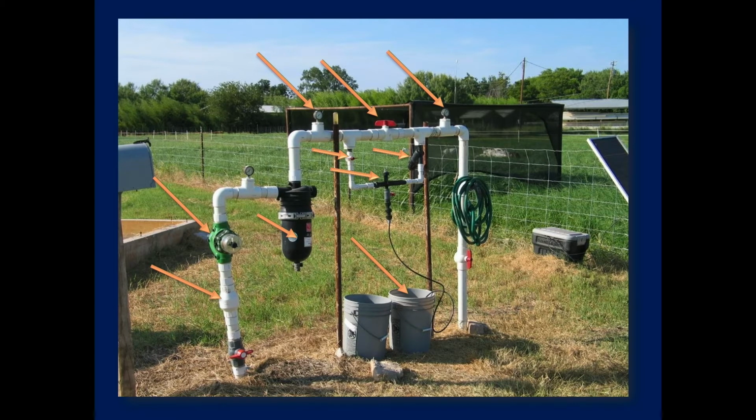This is a disc filter. In this particular case, this man has a well, and he had a lot of particulate in his well. This disc filter will help remove sand particles. So depending on the particular water source you're dealing with, normally below ground water sources simplify irrigation significantly. Once you have an above ground system, that requires a higher level of filtration.